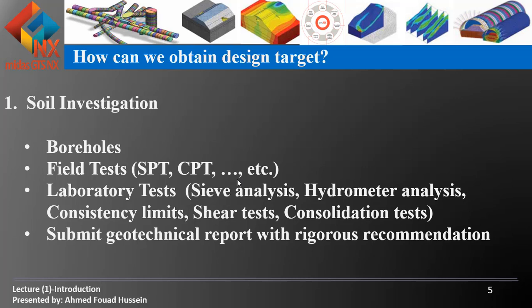So what is the liquid limit? The liquid limit is the water content at the transition between the liquid state and the plastic state. In another expression, in the Casagrande experiment, it is the water content which closes a groove of 25 millimeter length.